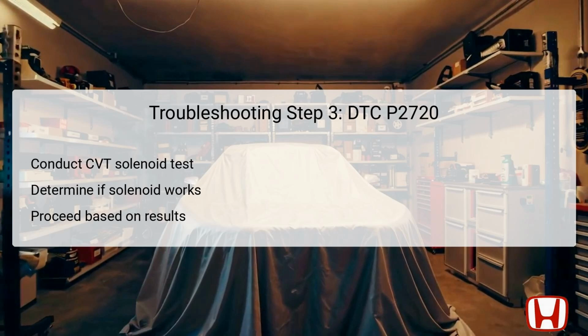If the solenoid operates as intended, the next step is to perform an open wire check on the lockup clutch control solenoid line. However, if the solenoid exhibits any signs of malfunction, the technician must proceed to the subsequent steps for more extensive checks and possible replacements. Effectively diagnosing the solenoid's condition is crucial, as it significantly influences the vehicle's overall driving performance.